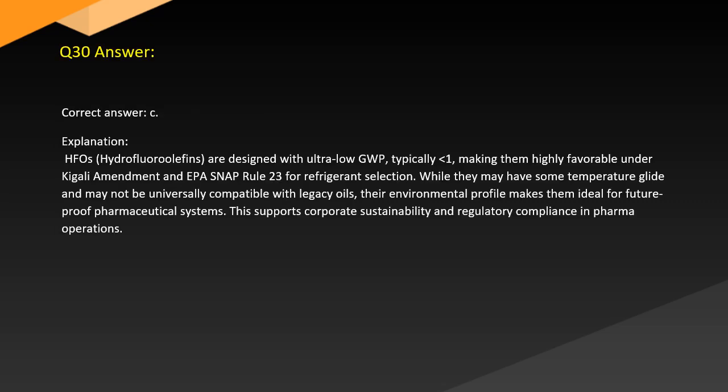Answer. Correct answer: C. Explanation. HFOs, hydrofluoroolefins, are designed with ultra-low GWP, typically close to one, making them highly favorable under the Kigali Amendment and the EPA SNAP Rule 23 for refrigerant selection. While they may have some temperature glide and may not be universally compatible with legacy oils, their environmental profile makes them ideal for future-proof pharmaceutical systems. This supports corporate sustainability and regulatory compliance in pharma operations.